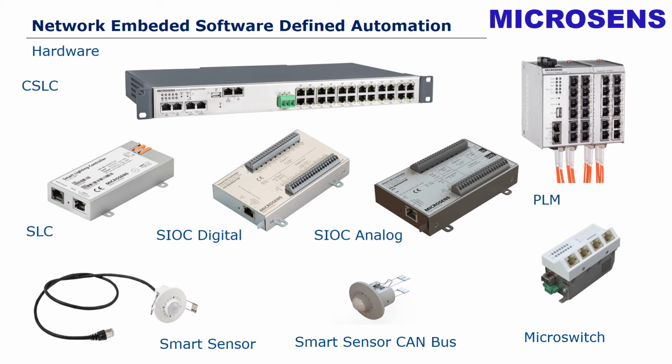On top we have the central smart light controller, as I described before. You see you have here RJ45 connectors where we can connect several LED lamps. We have here the connectors for the CAN bus, which is also using RJ45 and Cat5 cabling.